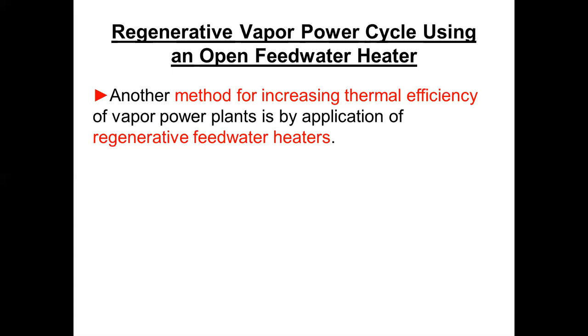Before it enters the boiler. So that's what these regenerative feed water heaters are all about. Once we start doing that, some books call it just the regenerative cycle. Other books call it the regenerative Rankine cycle. I typically call it the regenerative Rankine cycle because I want to make sure that people realize it's still a Rankine cycle, but we're buying extra hardware in order to make it more efficient. And that's the regenerative portion of it.